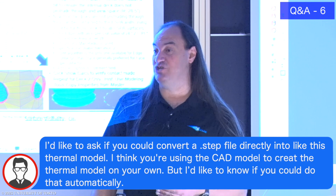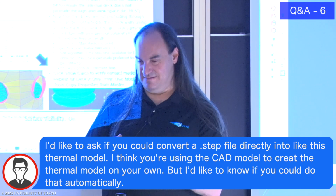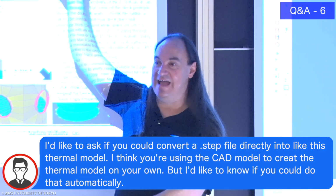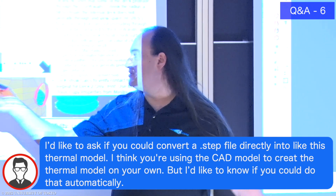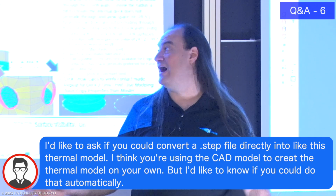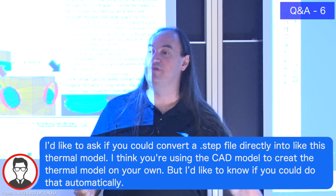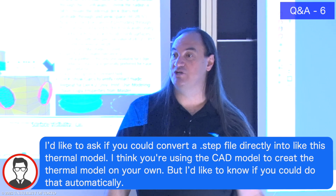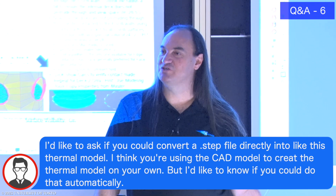And when you have radiation, 50,000 surfaces that all see each other goes as n squared, and suddenly your radiation coupling count goes very high, and your model runtime goes very long. So it may be quicker for you to push a button and get it, but it will take you longer to get results potentially than to do it manually. So I like to control how dense the mesh is myself rather than let the software do it. But there are times where an auto mesher is an appropriate path. Does that answer your question?